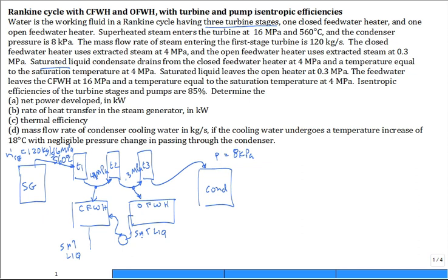In reality, anytime you have fluid flow, you have pressure drop in the direction of fluid flow unless you're converting kinetic energy into head. In fluids, you learn that as well. Here, it's called a diffuser. A diffuser, you can do that, increase the pressure. But just think about pipe flow. In pipe flow, you just go in the direction of decreasing pressure.